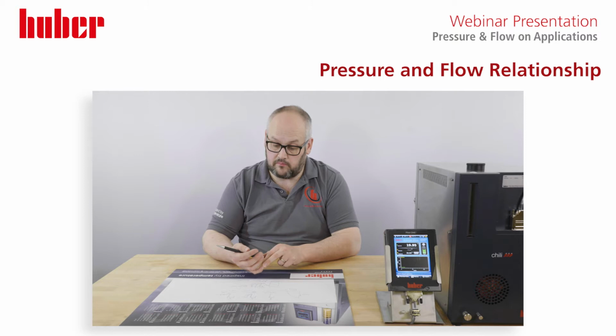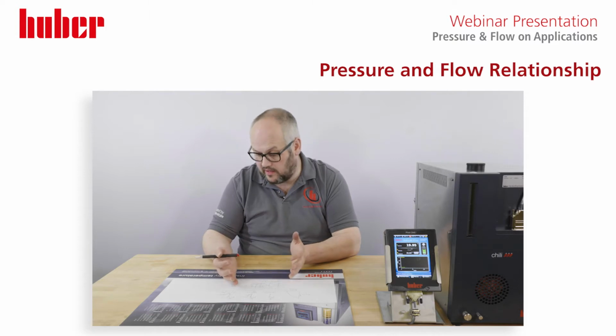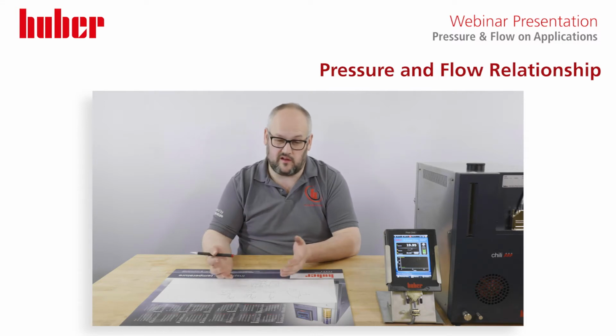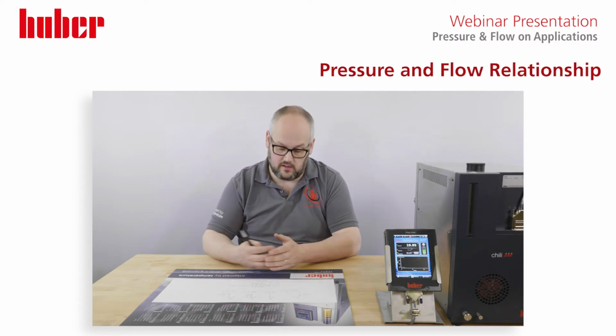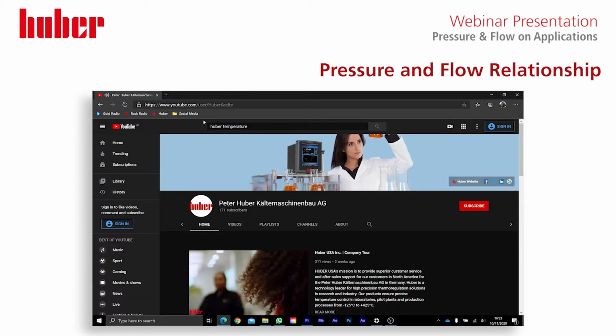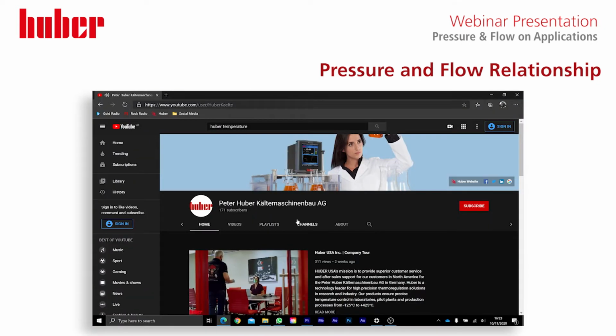In these units we do not have an inbuilt pressure sensor. However, we can adjust the pump speed. By adjusting the pump speed we can reduce the pressure being applied on the reactor system. However, as it's open bath, any expansion in the oil or additional pressure is seen on the bath. On the open bath systems, we do have a little quick guide on how to adjust the pump speed, and that'll be shown on the opposite side now.